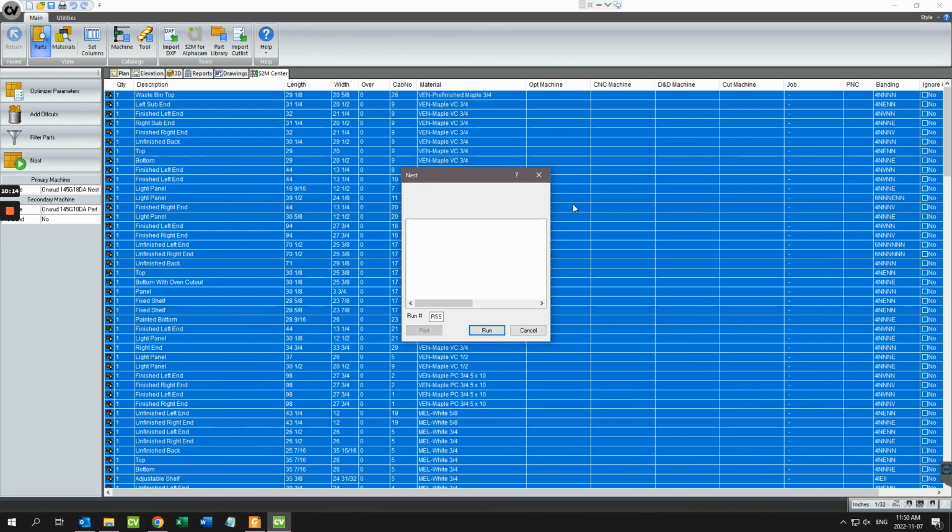And for all the parts, it will find the best places to put them on a 4x8 sheet of melamine or plywood or whatever it is the cabinet boxes are going to be built out of. The sheet goods are basically all of the parts that are required to make the cabinet boxes and end panels. So right now it's just thinking of where to put all the pieces. And it's pretty neat to see once it's all done. So I'll just press OK here.